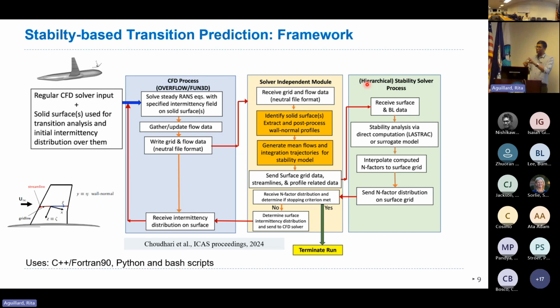Because right now, say you have a streamline coming from the fuselage nose and that's somehow coming back into the root of the wing, how to completely track that is not trivial. So your ideal way is to break it into surfaces, and each surface would be handled separately. But in those common regions, sometimes you'll have to give a separate section. But we do give the whole thing essentially.